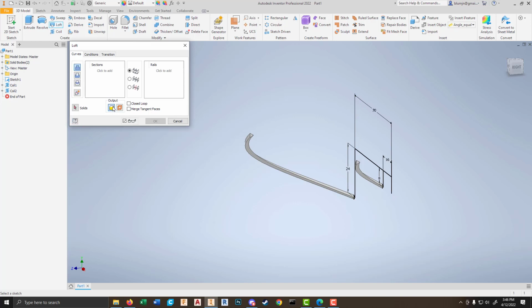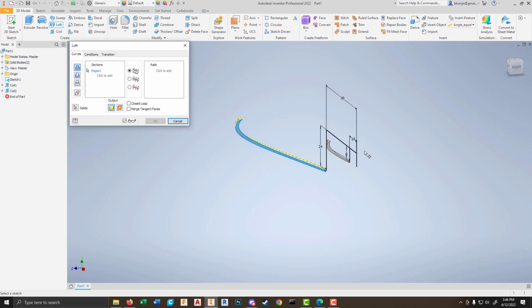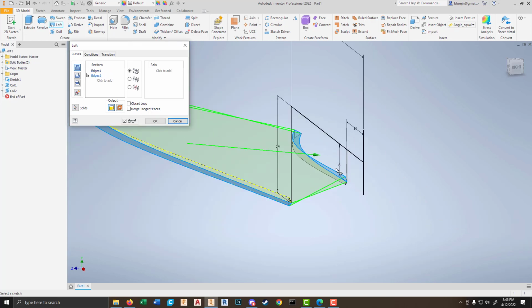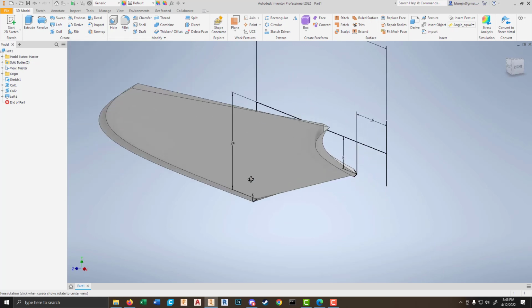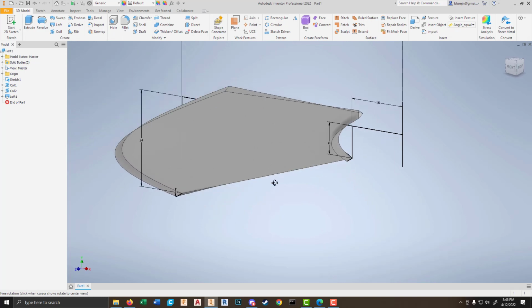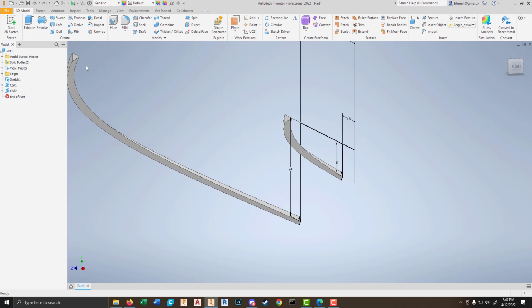And for surface, so for solid mode, I would need to be like, I want this surface, and I'm going to loft it over to this surface. Let's take a look at what that looks like. It creates this thing, which is actually not too far off of what we're going to end up with, but it's not quite right, so we're going to get rid of it. I just hit Control-Z, by the way, to undo.